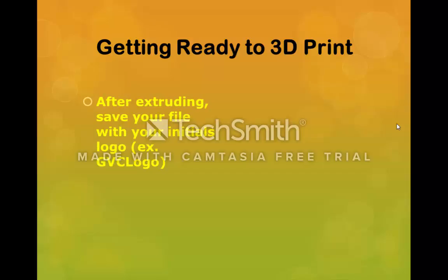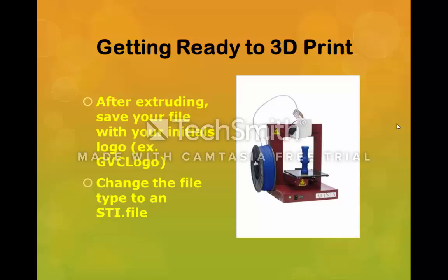After you've done your Inventor file and you've made it 3D, you need to save it and name it, and I want you to name it your initials logo. So mine would be GVC logo. Next, you need to save this as a different type of file. You need to save this as an STL file. This is something we have to do so we can get it into the software that our Affinia H480 3D printer uses.